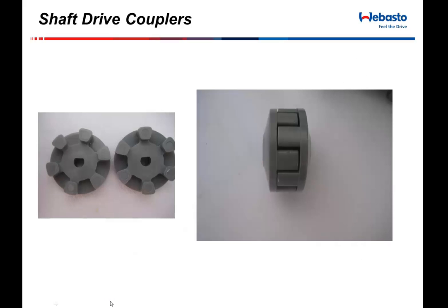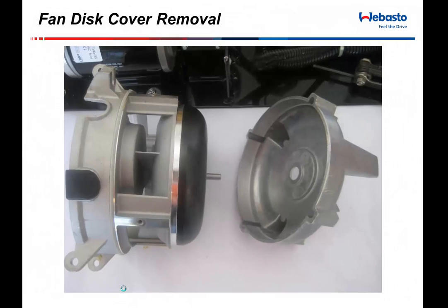If you do get something sucked up into the air intake, a large stick, let's say, if you get something put in there large enough and hard enough, it is possible to strip out these little drive holes, and at that point you'll have a free-flowing 12-volt motor turning, obviously, a very high-pitched hum. Those clutch halves connect to this shaft right here. In this picture we've taken off this cover, and we're exposing a fan, which is what is actually making a suction to bring the air in that's being used to burn.